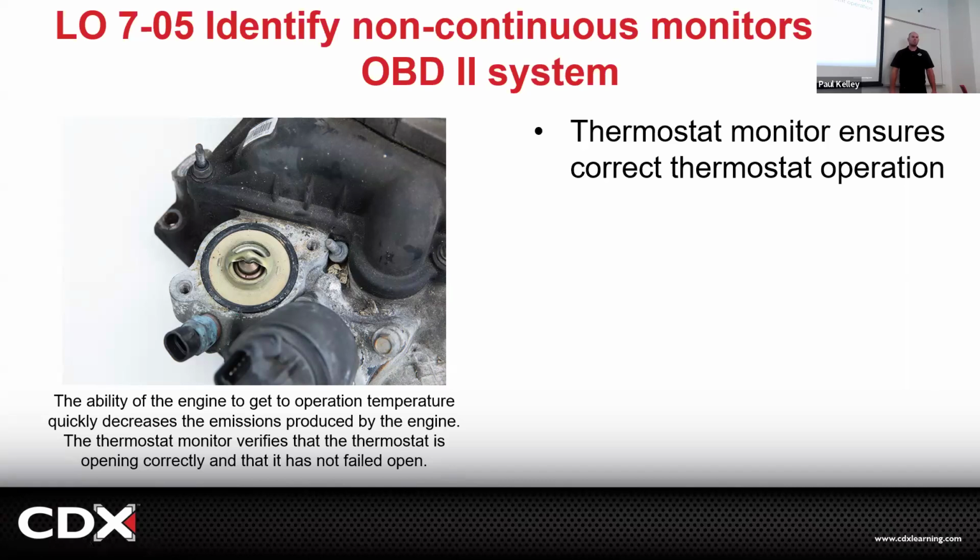And thermostats can fail sometimes. If a thermostat sticks closed, the engine overheats horribly on the side of the freeway. You'll lock that engine up, blow a head gasket, seize it, crack a block, crack a head. Thermostats failing are kind of scary. Nobody's ever had a thermostat fail? Oh, I bet some people have.